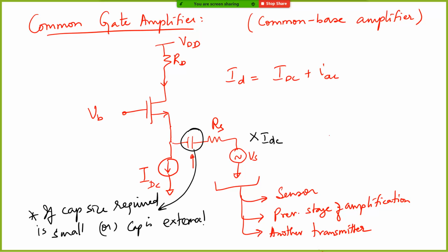Okay, so for example, if you are talking about audio frequency signals or some kilohertz, tens of kilohertz range signal, you cannot put a DC block capacitor on chip. Why? Because then you will have an entire chip just made out of capacitors, right? The density of capacitors is very small, very less on a chip, and therefore if you want some 1 microfarad capacitance, you cannot implement it on a chip.